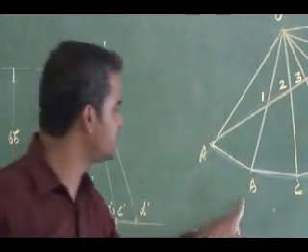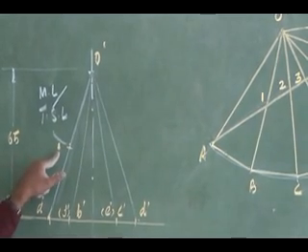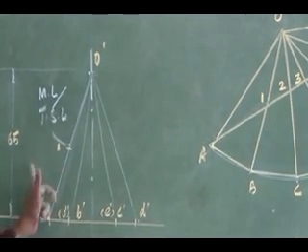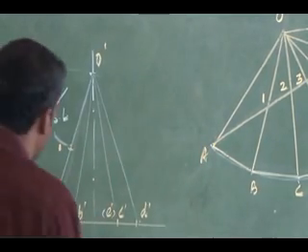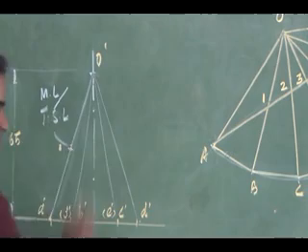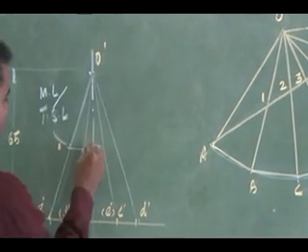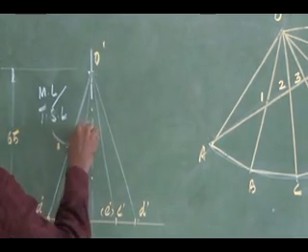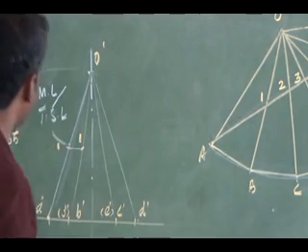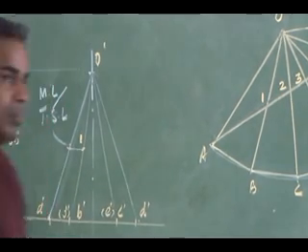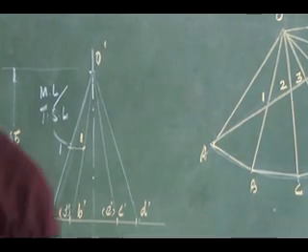Actually this one is on which slant edge? B. So I have transferred to the measuring line. Then I have to project it to the B slant edge. Okay, so B slant edge is there. So I have to project to that. That is my location of what? Actual location of cutting point 1. So this is not 1, this is a projected location. Right. Is it clear? Do you have any clarification in this step?